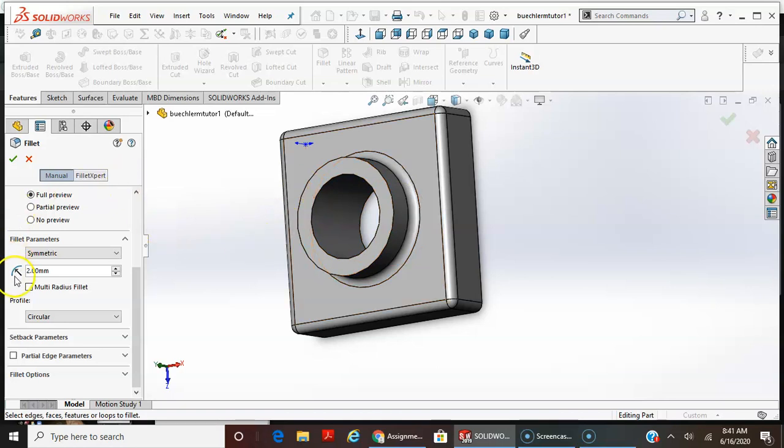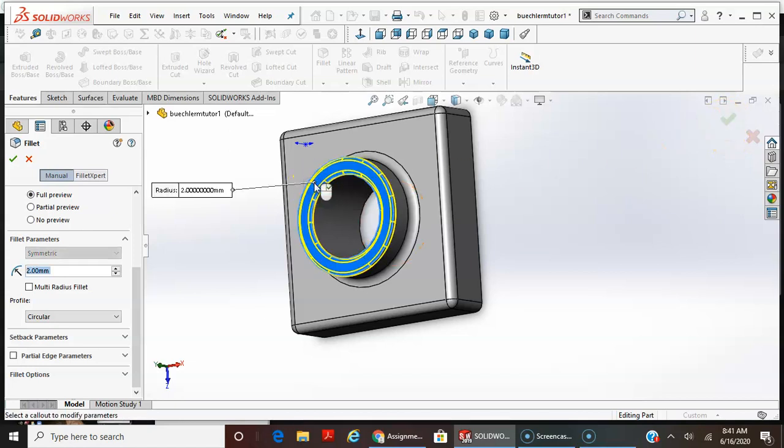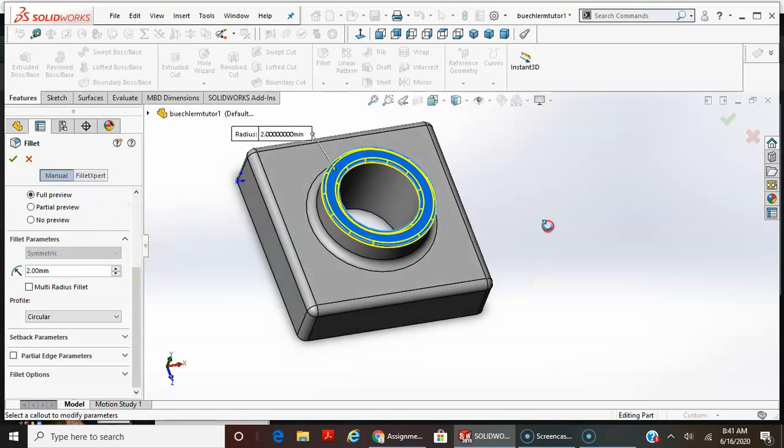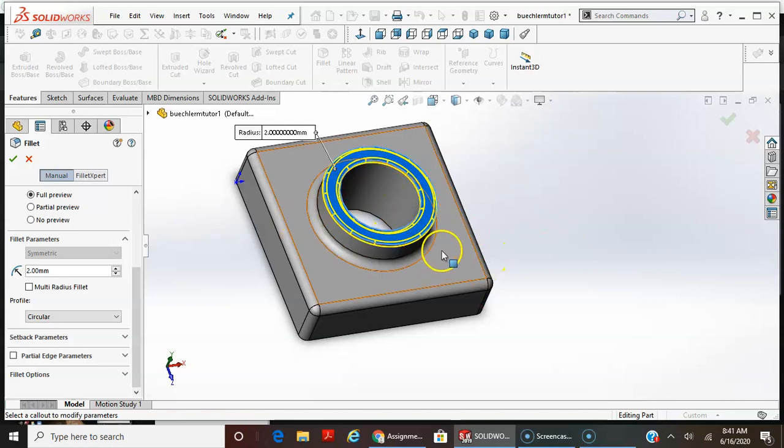I'm going to select for this fillet. I notice I'm in feature mode. I'm going to select this face. It doesn't really prompt you. Sometimes it prompts you for the selection, but in that case it doesn't prompt you for the selection, and I think that's not a user-friendly thing, and I'll mention that more throughout the semester, how the software could improve in the property manager on helping us determine what to select. But this looks good. I'm going to select yes.